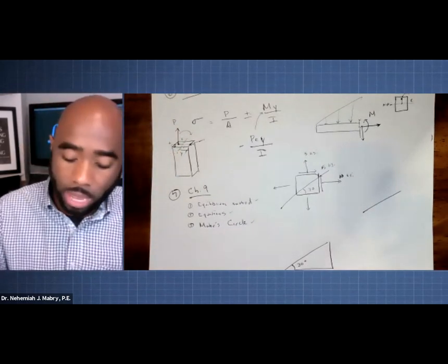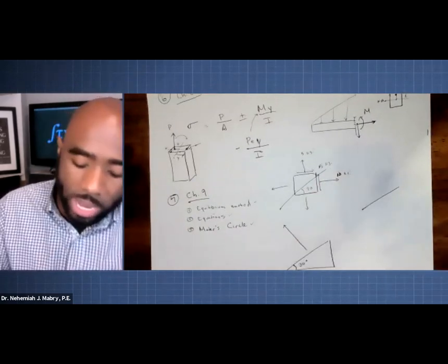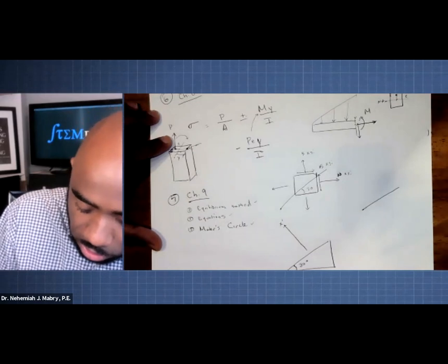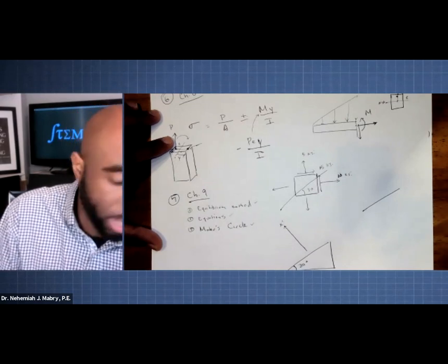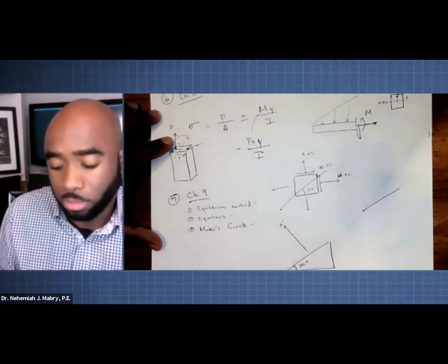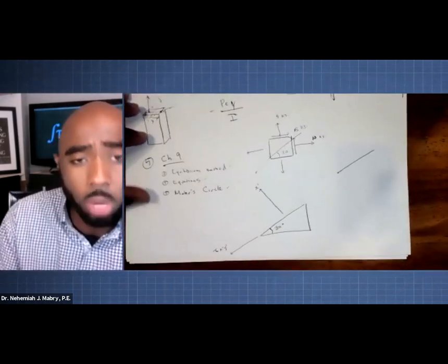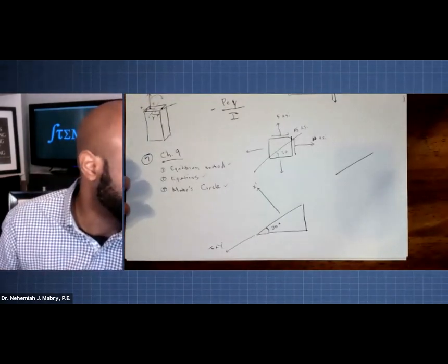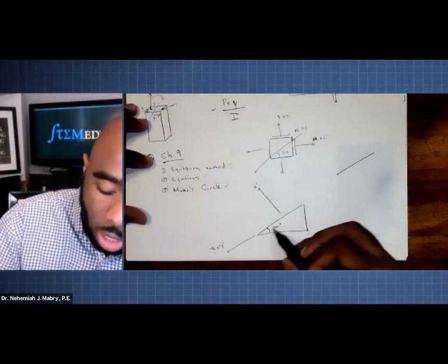And coming out the side of that, coming out this space, is always going to be our new x prime axis. And then parallel to that face will be our y prime axis, but this is also in line with our tau x prime y prime. So here, remember, here's what you've got to remember about the equilibrium method. What we're going to be doing is essentially summing the forces, or the stresses, whichever one you want to think about it as, whatever helps you, along each side.